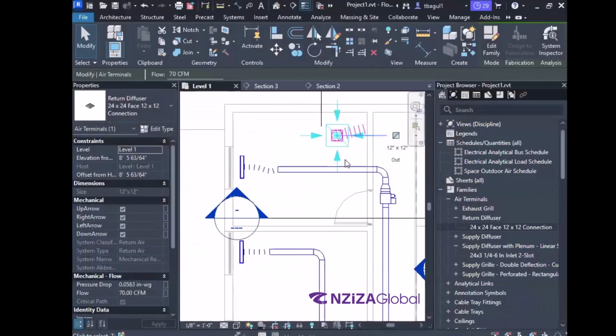Over here, the supply return air grill, we placed it on top, right? In surgeries, the return air grills are placed on the bottom. I mentioned the other day as well, we want to have a laminar flow, right? Plus the bacteria and the infections are usually heavy, so they settle on the bottom, and that is where the return will go back to the air handling unit. Did that make sense?